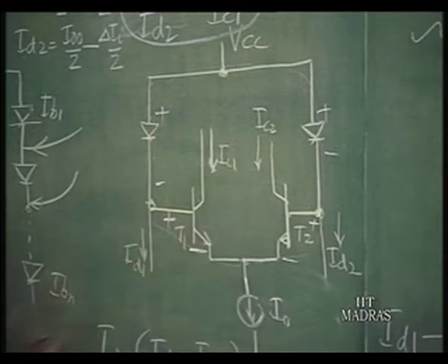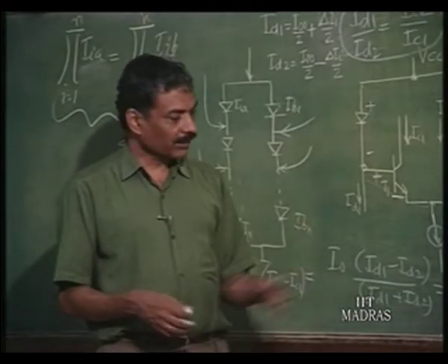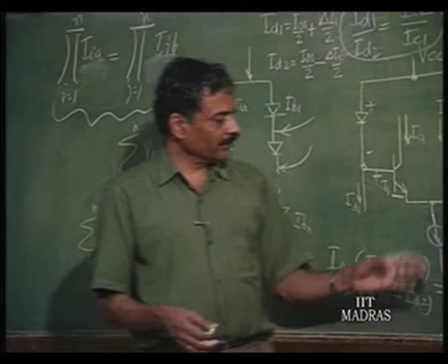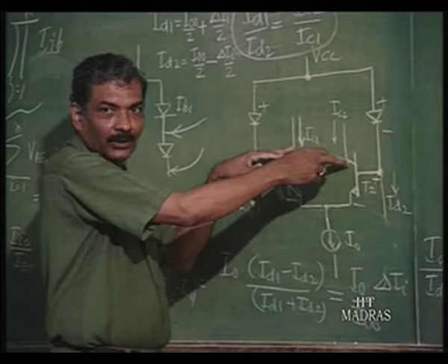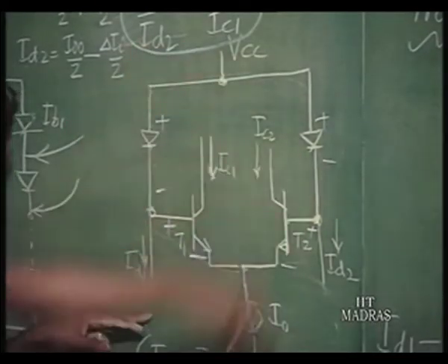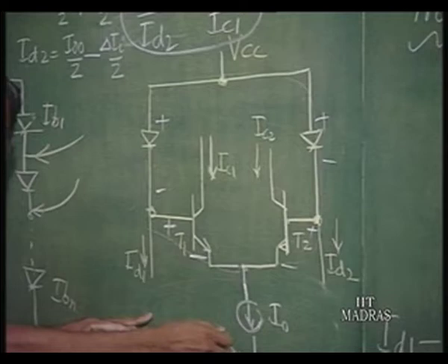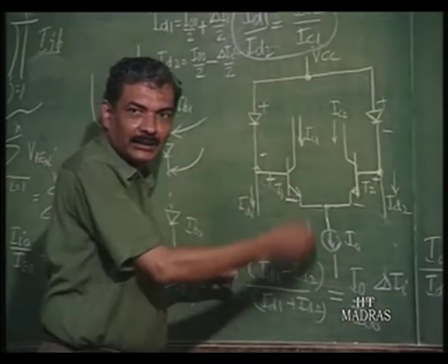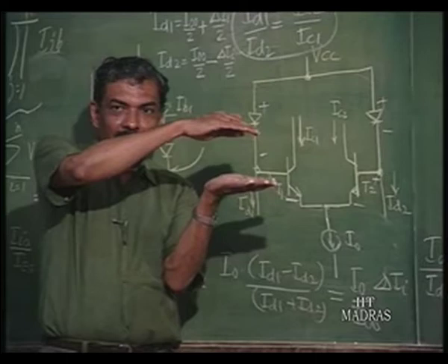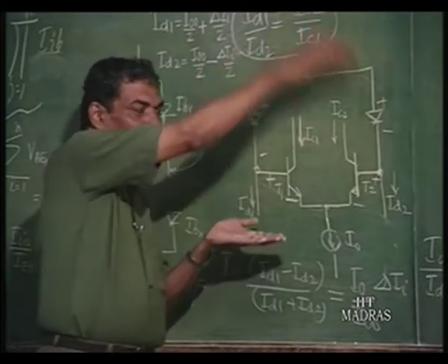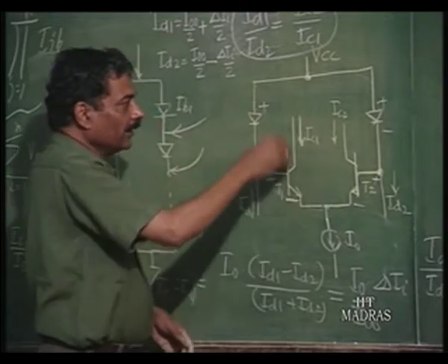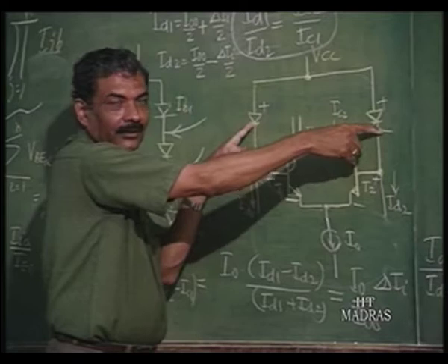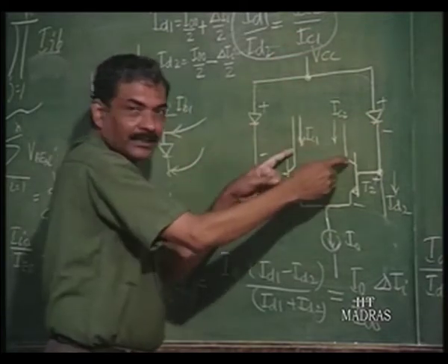So, these circuits are nowadays being used as wideband amplifiers with constant gain, and you can reach the required gain by simply cascading such structures, because this differential input could be the input to the next stage, which looks exactly identical. Only thing is the operating current of that is, let us say, 10 times more than this. So, you can put one structure over the other structure, that is why it is called a cell.